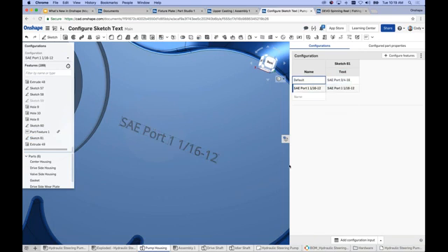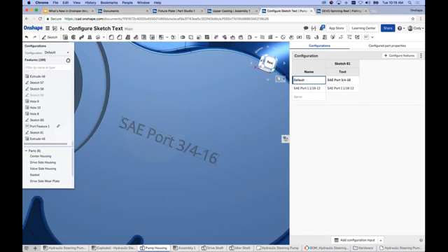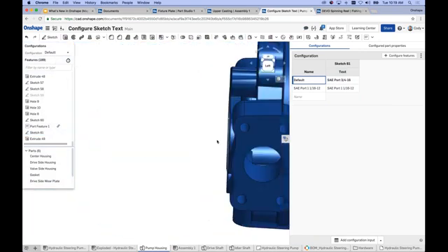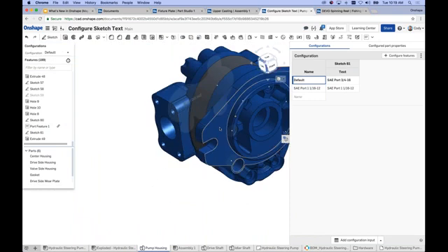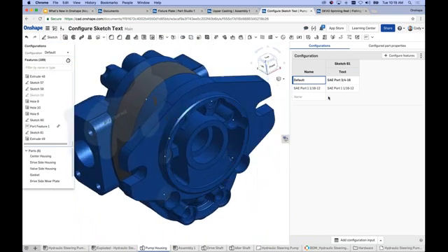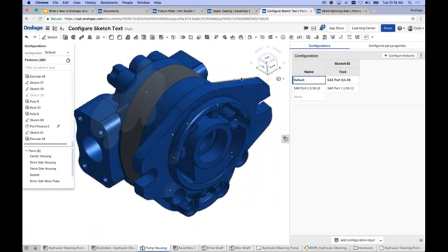So that's really it. If we switch back, you'll see it update here. Again, we're just controlling the text input based on these configuration inputs. So that's the key thing to stress. That was not possible in the past. In the past, you had to edit the sketch every time you changed the configuration. This is really specific, of course, to those that do configurations and those that need configuration values linked or in some way driven by configurations.